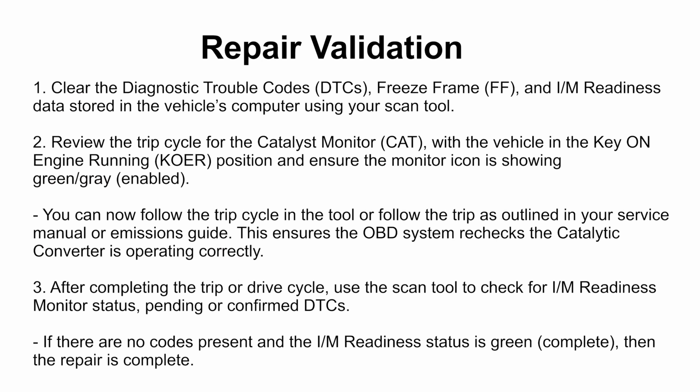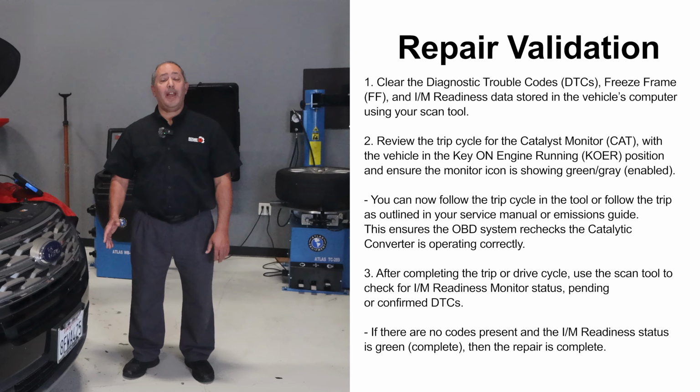Now we'll perform repair validation to confirm everything is working correctly. Follow these steps. The first step in your repair validation is to clear your diagnostic trouble codes, freeze frame data, and your I&M readiness data stored in the vehicle's computer using your scan tool.